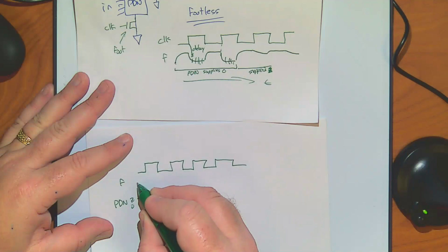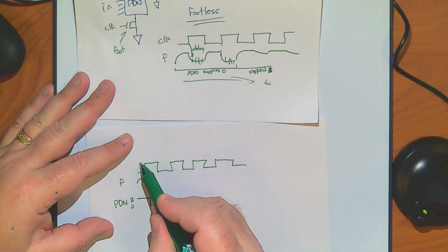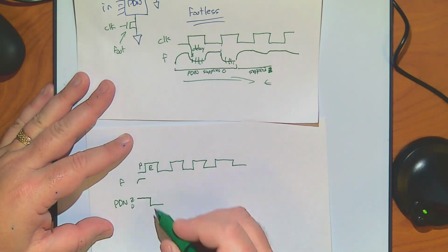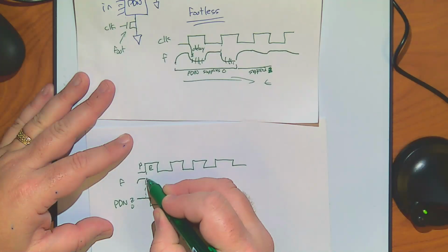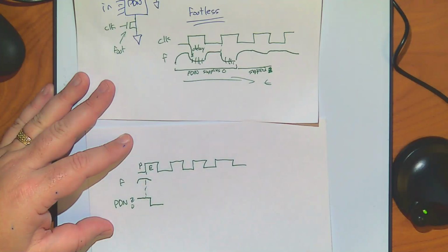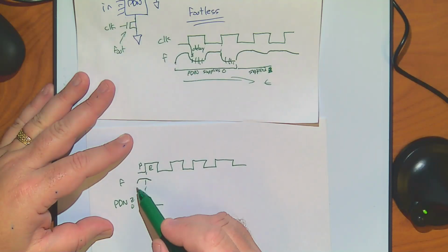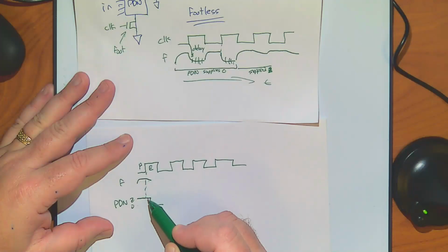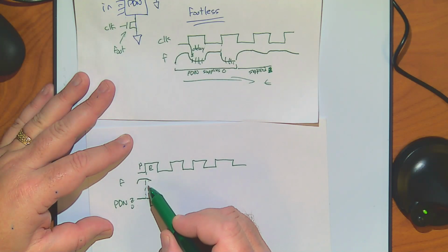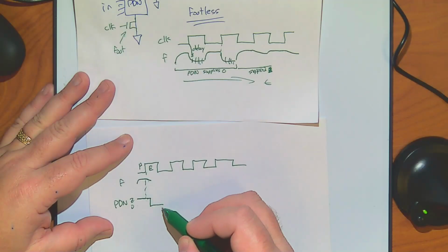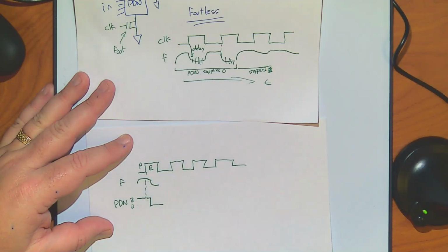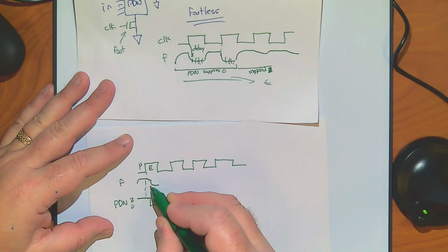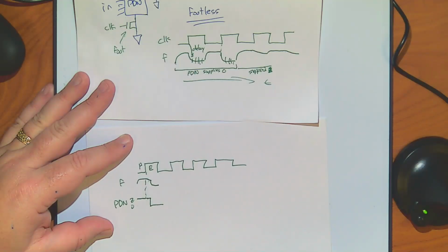So here on F, it charges up during the pre-charge. When I go to the evaluate stage, it's still Z, so it's slowly discharging. Initially, it's supplying Z, disconnecting me from ground, so I'm slowly discharging out through the system. And then all of a sudden, it connects me to ground. Whoosh. So it gave me a 1, and when it transitioned, it went pretty quickly to 0, didn't it?